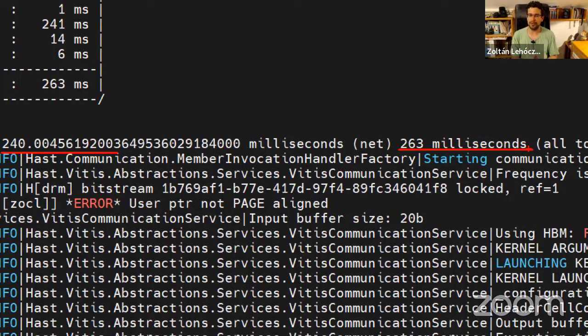So roughly what we see here is that on the FPGA, the same algorithm took around a hundredth of the time. It was 100 times faster. Now, your mileage may vary, and this is, again, a synthetic example, but still it shows you what's possible. You can get even a 100 times speed up, but something like a 10 times speed up is quite doable as well. And you get the same thing with a lower power consumption, which again translates to lower costs.